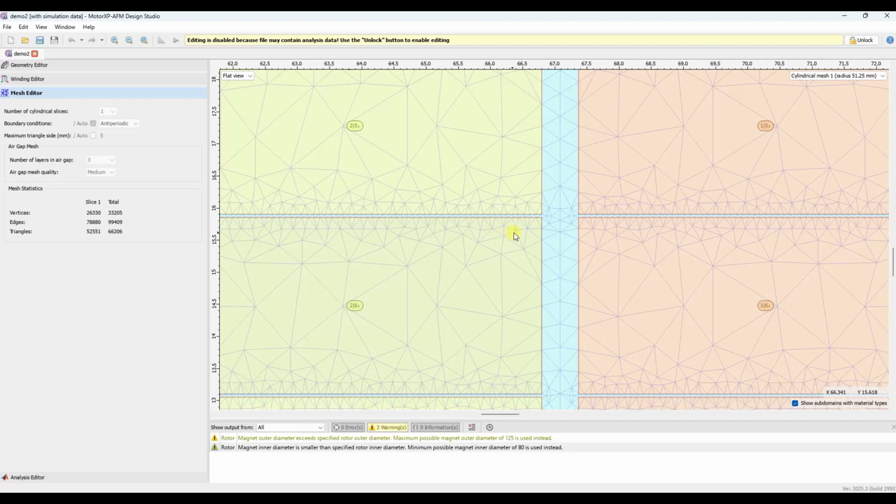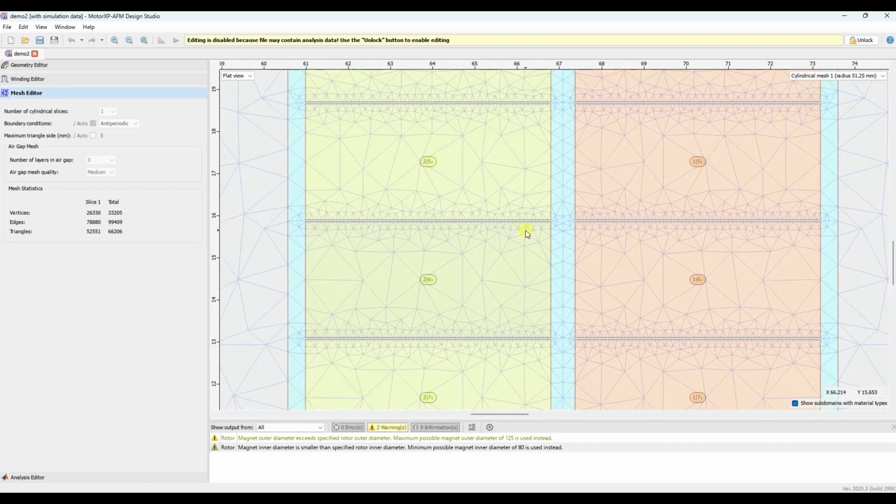Although skin depth mesh is a bit different from this, because the layers of the skin depth have kind of exponential decay. If you have a skin depth mesh with like three layers, the separation between layers is a law you need to follow, which is an exponential distance. So usually you have a calculator to determine this. Okay, I understand.